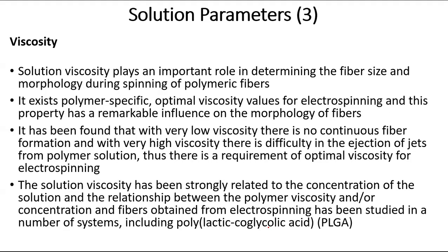And then viscosity is another solution parameter. The solution viscosity is very important in determining the fiber size and the morphology. There exists a polymer-specific optimal viscosity value. The concentration and the molecular weight basically govern the viscosity.